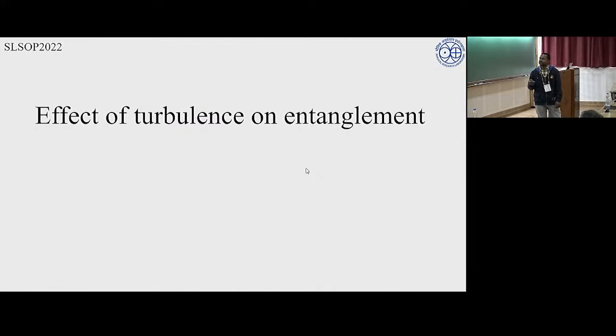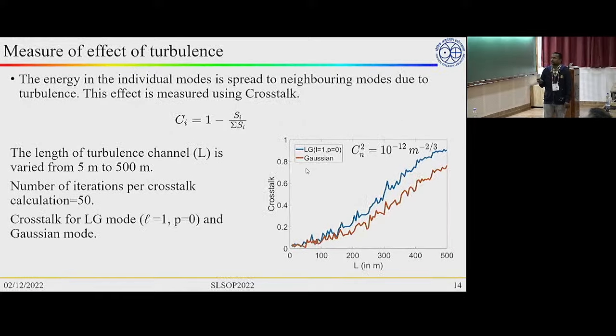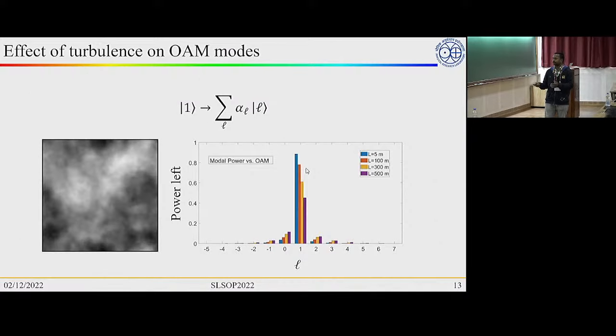Moving forward, so this is, okay. So SI is the total intensity left in that mode versus all the modes. So this is generally 1, and these are whatever is left. So as you increase the distance, what will happen? This will become closer to 1. Because this becomes 0, as you increase the distance, the intensity left in that particular mode will be less. So SI will become 0, and if you calculate all the side modes, they are equivalently 1 because you are not losing any photon here.